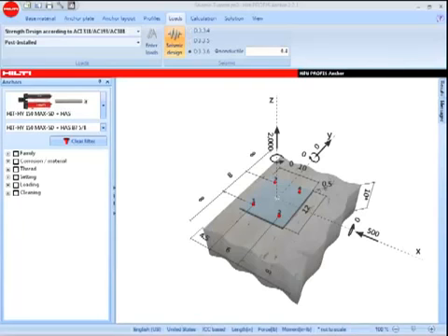When anchor design includes the provisions of IBC 2009 Part 1908.1.9, PROFIS Anchor users can input a value for phi non-ductile equal to 1. This will permit an anchor design that includes both ductile and non-ductile anchor elements for non-structural components or anchors designed to resist wall out-of-plane forces.